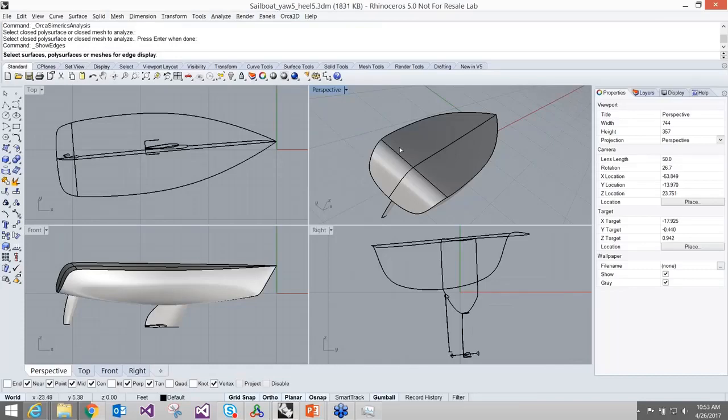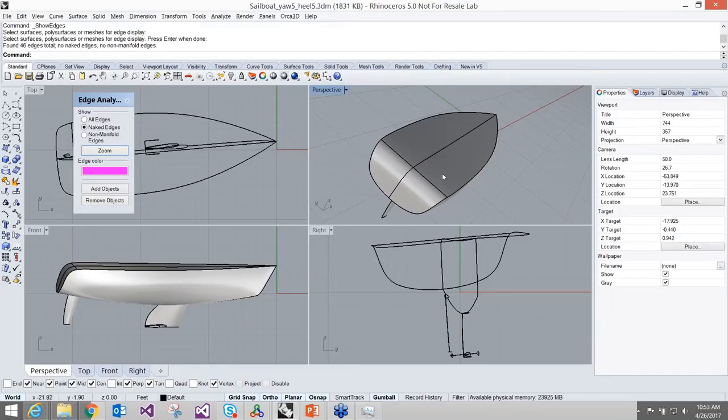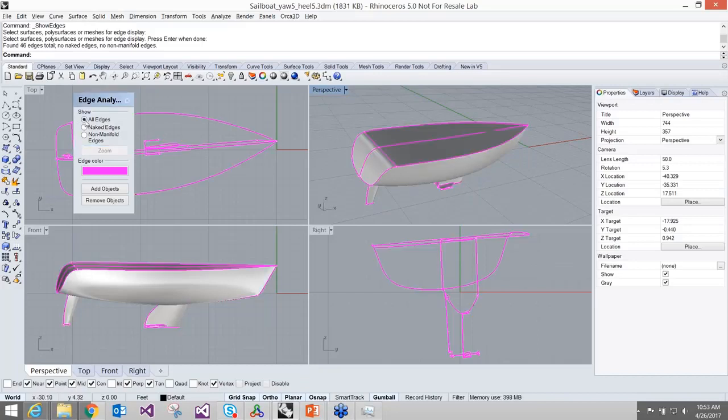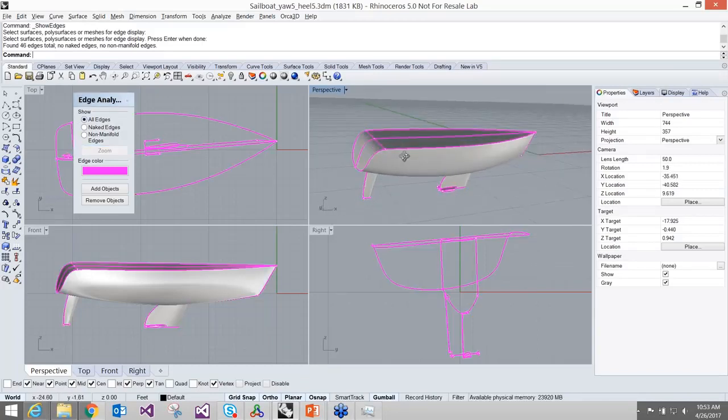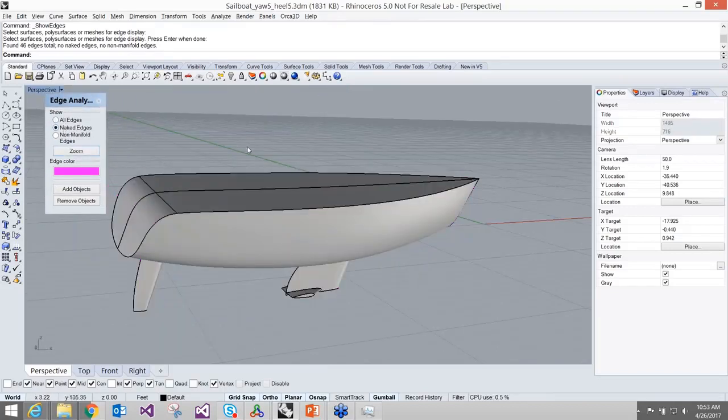You should also consider whether you should simplify or de-feature your model. So we showed an example with the superstructure there, which is nice to see the airflow around the superstructure. But of course, that increases the size of the CFD mesh in terms of cells and slows things down. So if you're not interested in that particular aspect of the analysis, you can do something like the model that you see here, where there's just a simple flat deck. In terms of the hydrodynamics, it will have very little effect, but it will increase the speed of the solution.